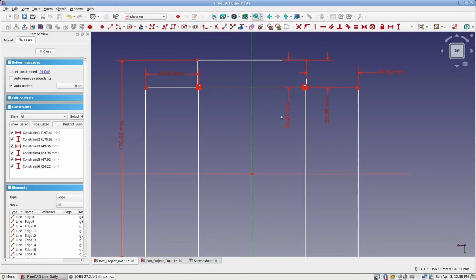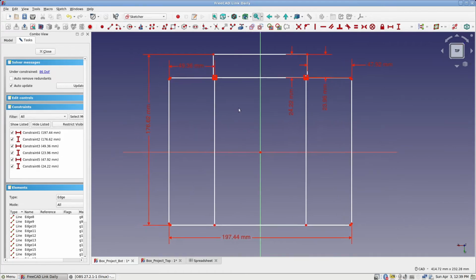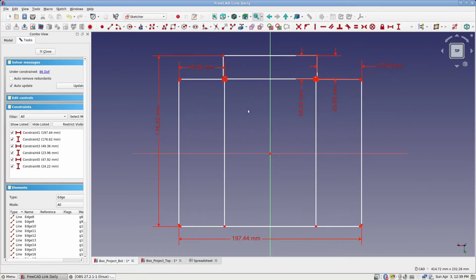So this dimension and this dimension is what you're going to notch. This notch and this notch over here are the same size, so we don't have to bother with that. But that pretty much gives you all you need to know to blank this piece out and cut the notches and then do your 3 bends.